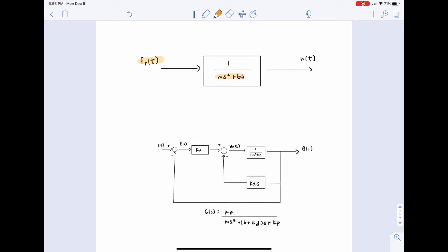The open loop plant will experience disturbances from outside forces. The primary force impacting these functions of the system is gravity. When implementing a design for the plant, disturbance from the gravitational force will have to be accounted for. This is shown in the diagram below. This is the example of the PD controller that accounts for the force of gravity acting on a UAV.